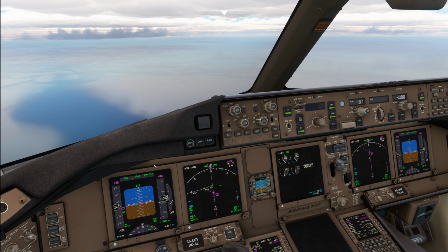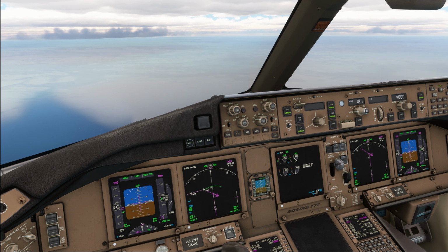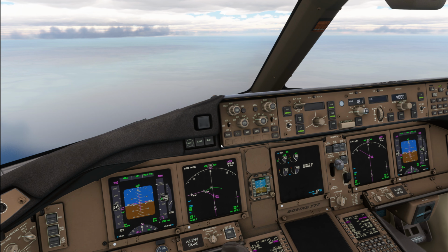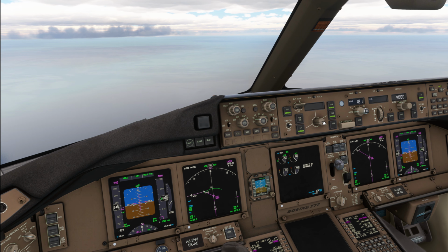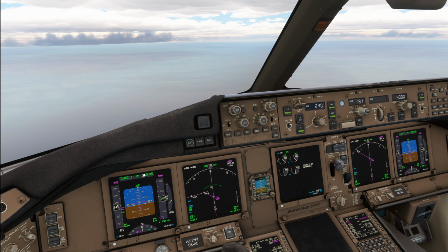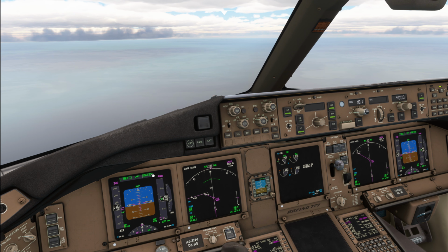So, coming in on the approach, we try to maximize the use of the autoflight system, that's LNAV and VNAV. Only for a localizer approach we would be using localizer mode. Maintain good control of your airspeed, and Boeing does recommend that you don't keep the speed window closed, but that you actually open it up. But don't do that too early, since opening the speed window too early while the FMC is not yet in approach logic is going to give you VNAV speed. So let's go ahead and close that again, so that we remain in VNAV path mode.